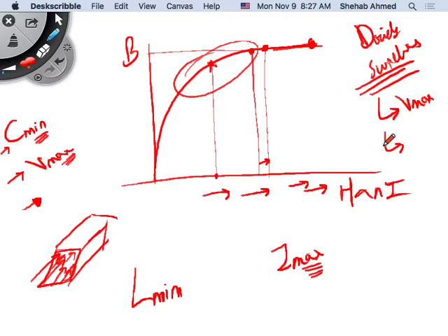But you had to first filter a first set of components that you were going to start looking at in more detail. So it depends on, in the switch, it was maximum voltage because of the breakdown of the switch's insulation, as well as the average current. Remember? We said average current causes heat. Right? Average current is what's going to cause heat. So you have a switching current waveform. Current in the switch looks like this.